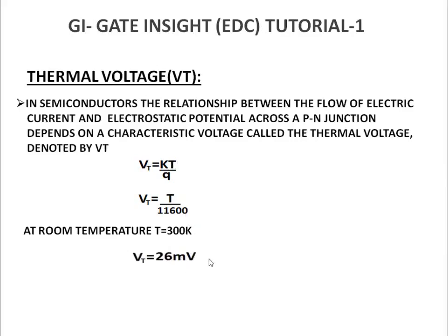Now remember that this is the standard value, and this value you're going to use in your problems. If the value of Vt is not given, then use Vt equal to 26 millivolt, and if the value is given, then use that value in the solution.